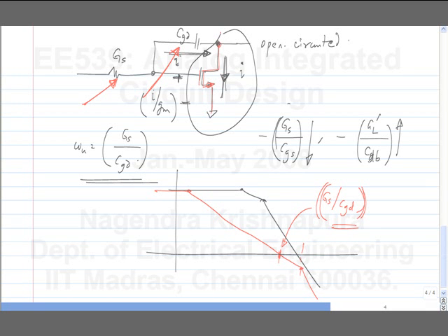Now, because of all these parasitics, you will have some values of poles and zeros. So, the analysis lets you know which is responsible for what, which capacitance gives you what kind of pole. Or you can think of it as some sort of design exercise where you manipulate the values of different components to get the response you want.